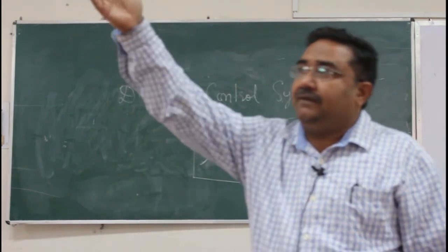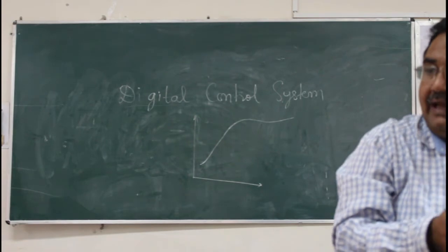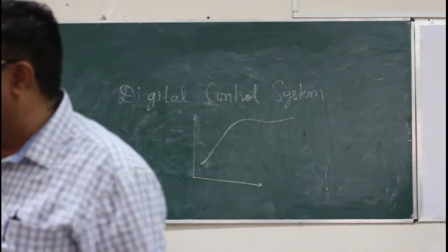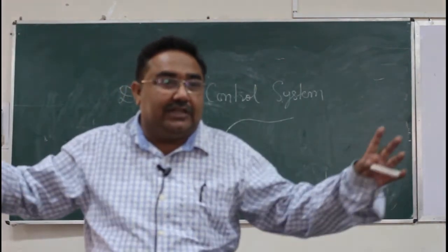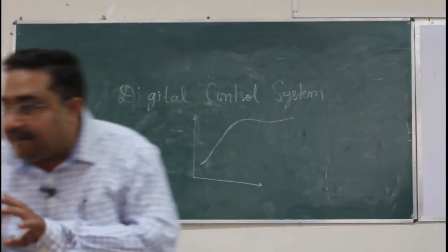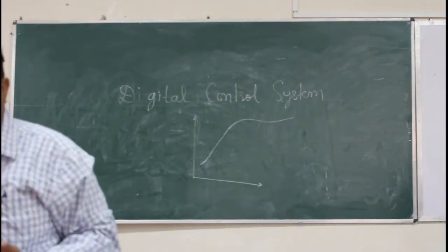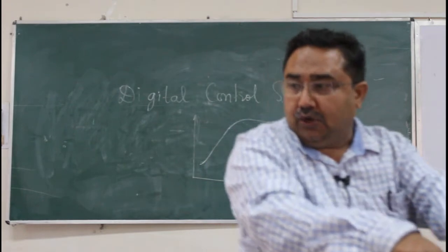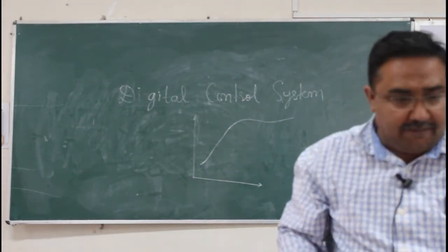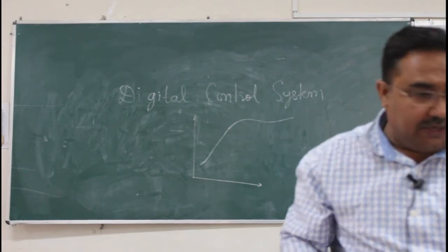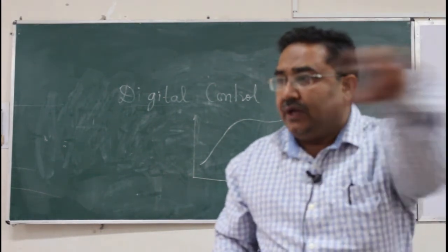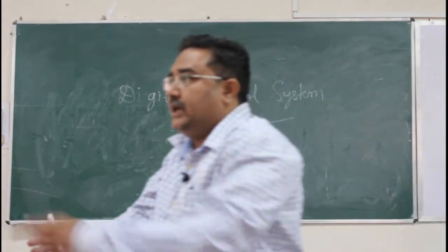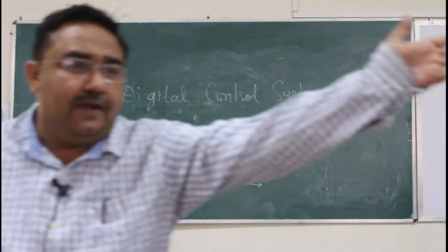What will happen? It will take the input supply. Clear? And now it will convert it into digital form. Because of this advantage, processing is fast. It will immediately take it. Now in my saying and describing all this, it takes seconds, minutes, but practically all these things happen in milliseconds, microseconds. Is it clear? It will take the input, convert it into binary form, and then go to the controller. The controller says this is the input, he wants this much output, 1000 RPM. So accordingly he will find out what voltage is required. So he will give it to the chopper or converter. The converter will reduce the voltage, convert it again into analog input, and give it to the motor.